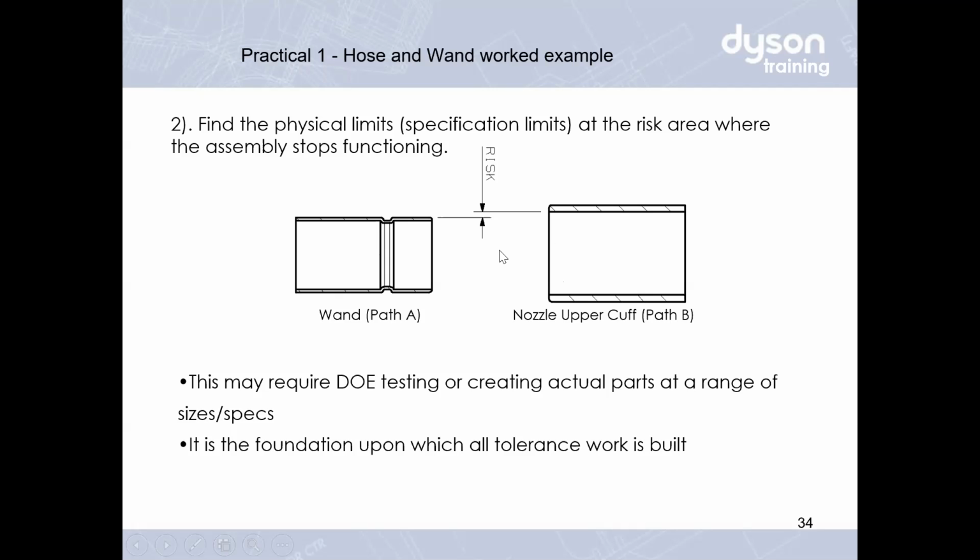And therefore, I repeat, the system requires us to design something so that when we assemble, the force is 3 to 5 Newton. So what are the dimensions? That's done in system design. Next is parameter design. What dimensions are we going to control to make sure that I can control the 3 to 5 Newton? I want to control, for example, this length.